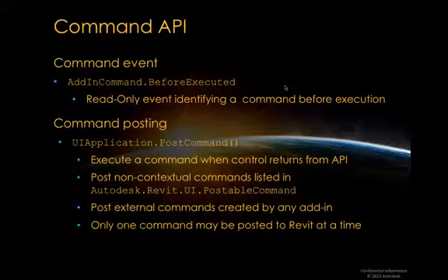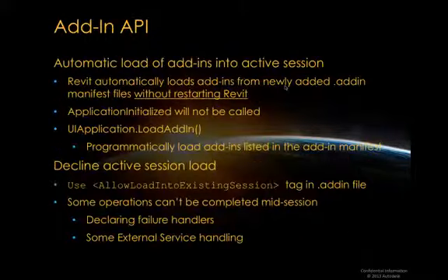You can also post external commands created by your own or other add-ins. You can obviously only post one command at a time, and the command will only be executed after the control returns from the add-in which called the post command method. There is also a command event which notifies you before an add-in command is executed.